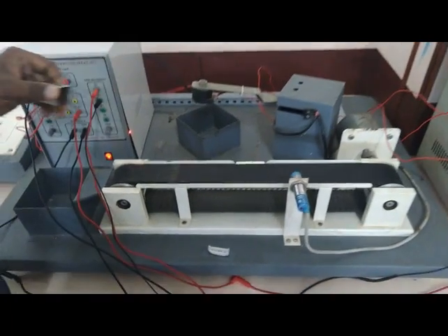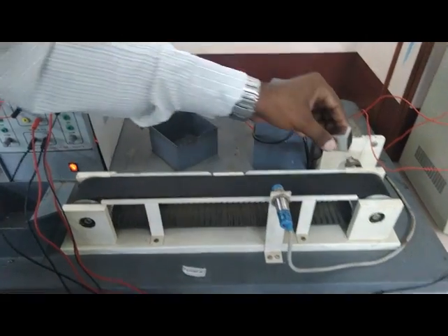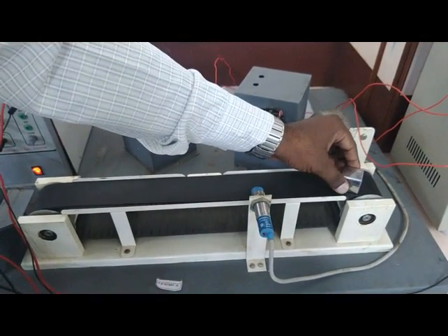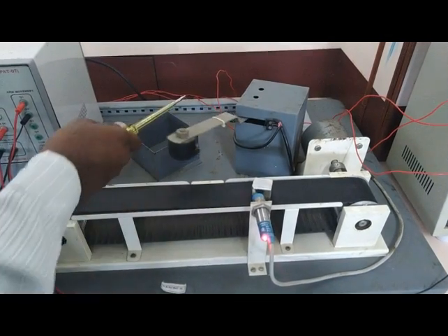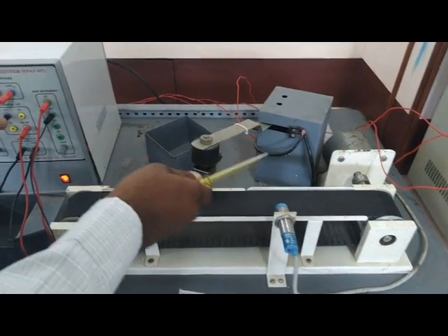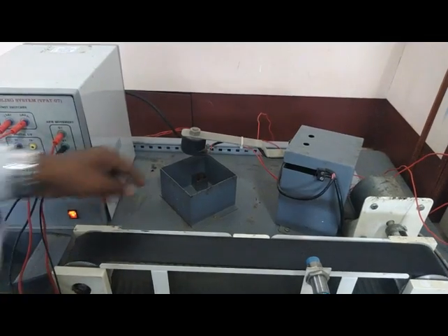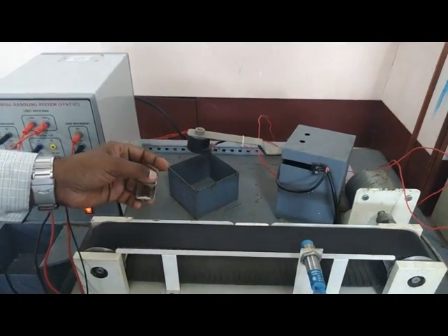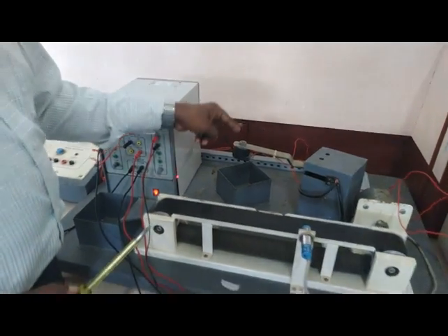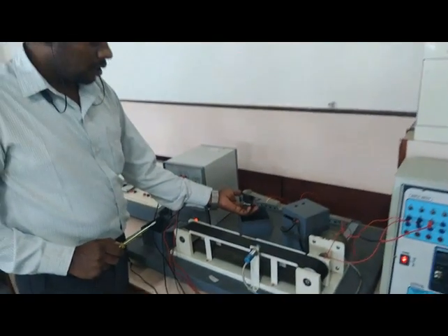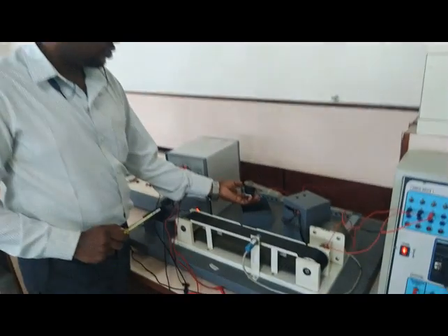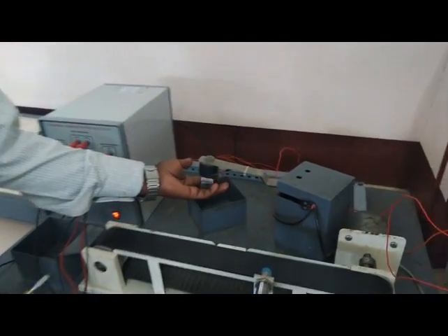So the entire module is running now. The conveyor will bring the material from the source point. When the material reaches our proximity sensor, the robo arm will move in the forward direction. There are constraints we developed in our program. When the robo arm is in forward direction, this electromagnetic switch should not go high; in the sense, it should not pick any material.